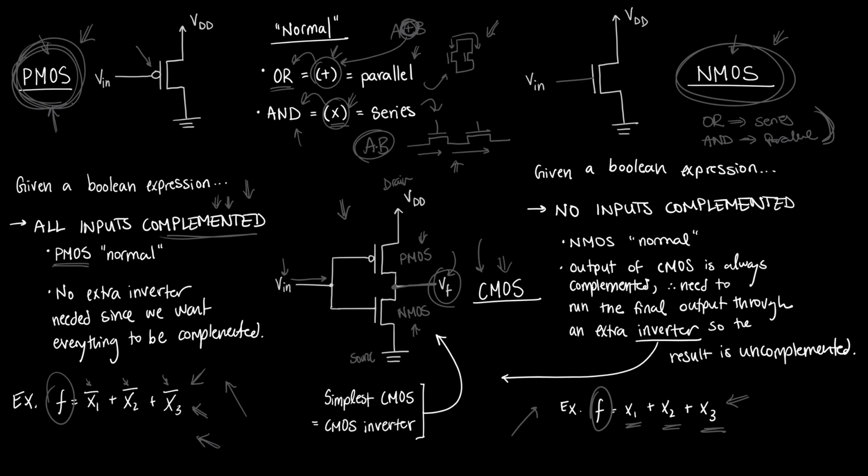And in this case, another thing to know here, I know it's a lot of information, is just that whenever you construct a CMOS circuit or a CMOS gate, the output is always going to be put out complemented. So if I were to simply draw the parallel circuit for this with PMOS, connect it to the series circuit for NMOS for this function down here, and take the output of that, that would be fine. That would be the inverted output because all of these pieces would be inverted, and that's the goal with this because they're inverted in our function, so it will properly represent the function.